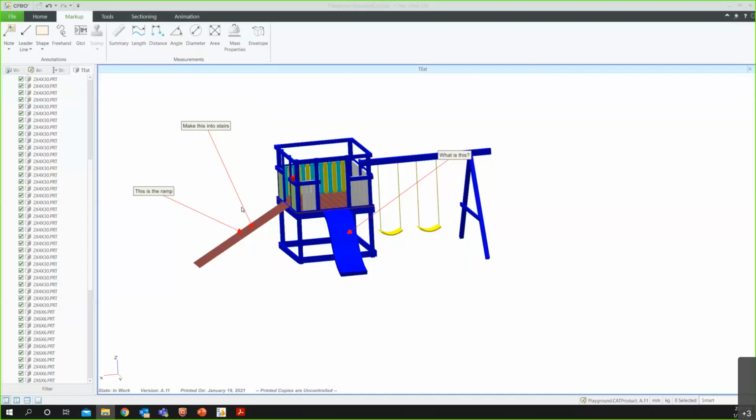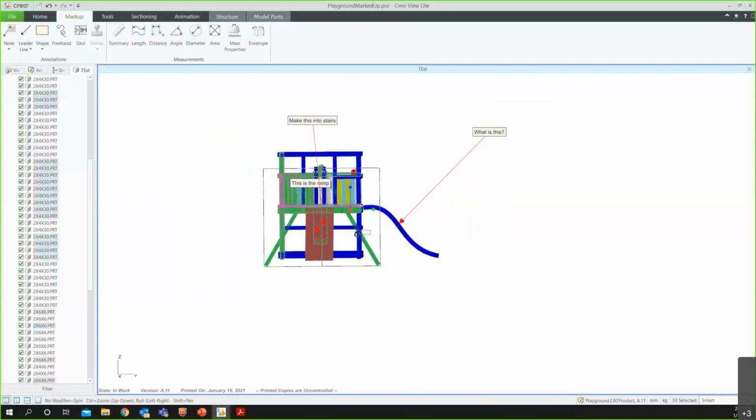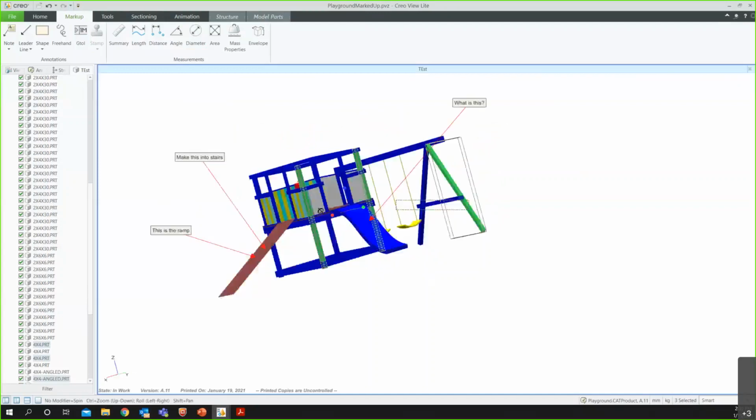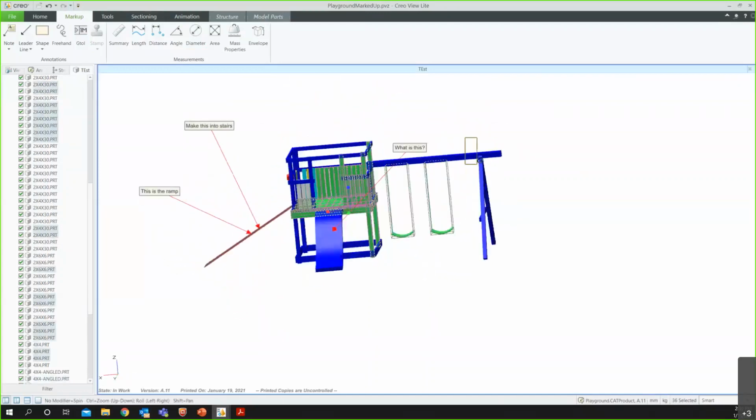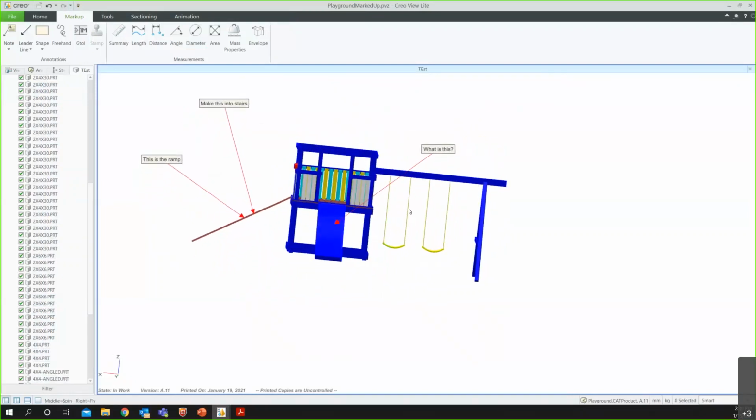So if you think of a front view, side view, left view, you can save a state and then make that basically like a checkpoint that someone can go through, click on, and it would, I click on left, then I click on front, it'll automatically spin it over, and the combined state will also control the visibility. So if I had chosen when it's in this view to hide certain elements, those would also be hidden.